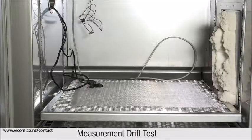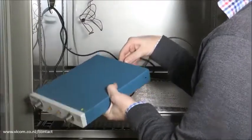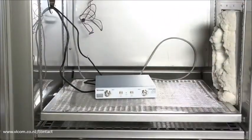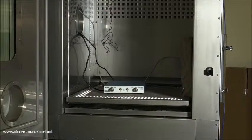When it comes to VNAs, drift errors are how much the measurement changes over time due to changes in the test system caused by heat, vibration, or instabilities. This test will serve as a figure of merit for how well the instrument maintains its user calibration over time in stable environments. This is important in many automated manufacturing applications where less drift means greater measurement stability and less time having to spend recalibrating your measurement system.